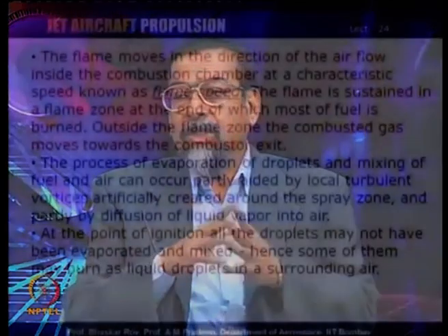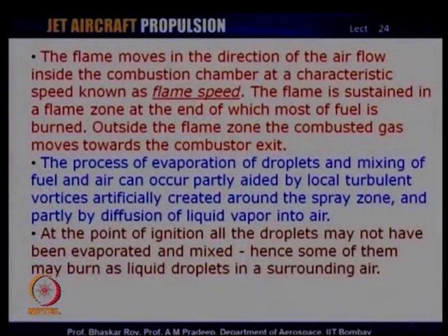Now, outside the flame zone, the combustion gas moves towards the combustion exit. This movement of combusted gas towards the exit is often aided by the motion of cold air that is coming in, and that is something that needs to be engineered into the combustion chamber design.